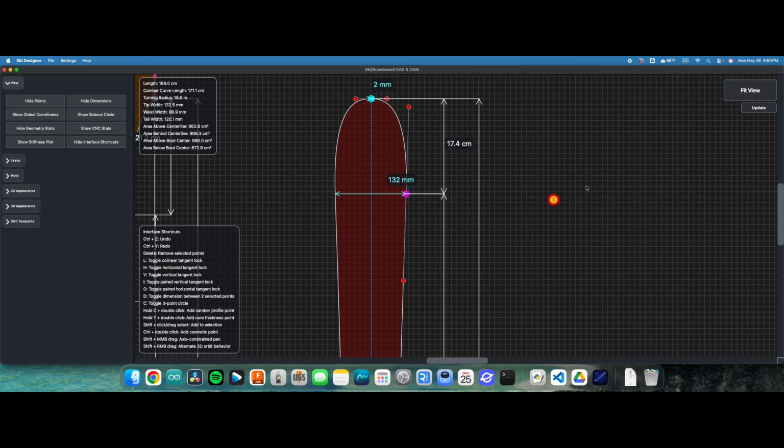For some more abstract design needs, you can hold down Control or Command on a Mac and then double click to create these little virtual points. When you select any 2 points, it creates a line and a dimension between them. Hitting D locks that dimension.